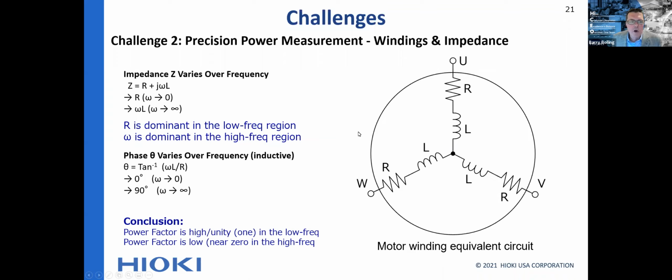The typical load, challenge number 2 here, is going to be power factor. And at low frequencies, these motors have easy power factor. I'll show you a graphic for that. At higher frequencies, such as the switching rate frequencies and the harmonics of the switching rate or the carrier, this load looks very inductive. So this is a typical load of an inverter, and that's why we chose it. It's challenging to measure at those high frequencies, and it's easy to measure at the low frequencies.